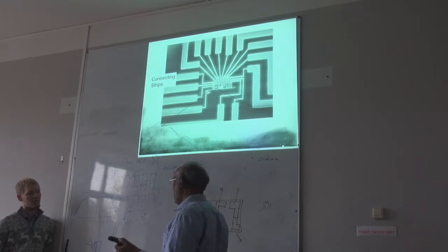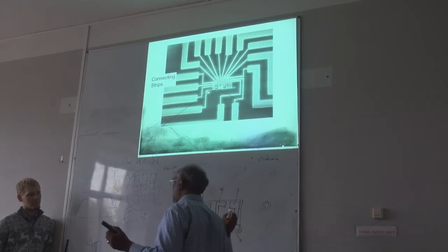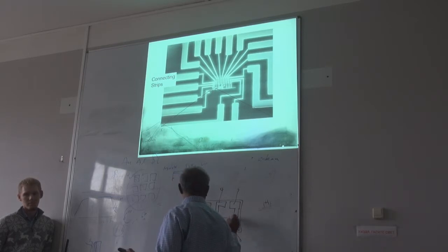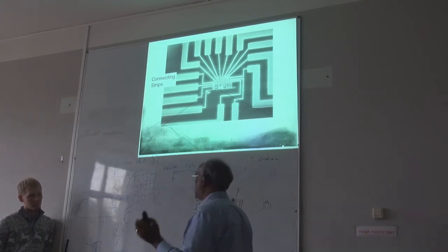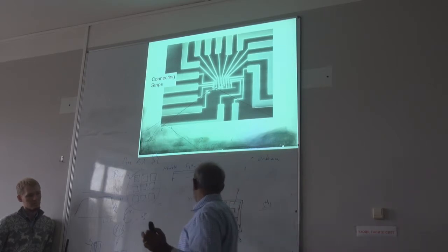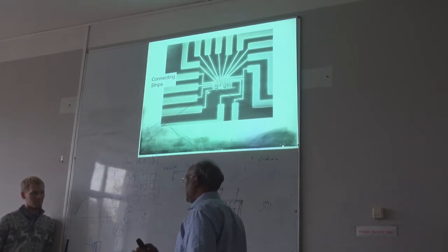So there can be more. That's why what we did was, you just grow nanotubes, so that one nanotube can be here, maybe another nanotube here, another nanotube say here. So now, first you do the AFM or something, so then I know the location of the nanotube. Because I have these alignment marks here, I have a good idea where the nanotube is.